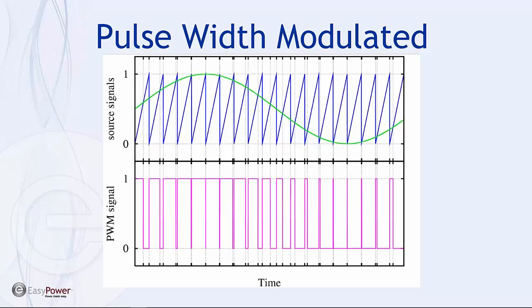I think the most common is pulse width modulated, and the primary methodology for determining how wide the pulse will be. So what the motor will see is a series of pulses with different widths on the positive and negative side of the swing.